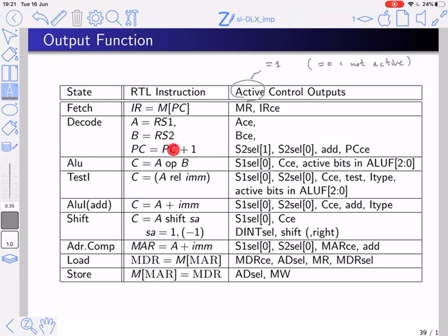And so you're adding a PC and 1, the output of the PC and the constant 1 are added, and the outcome of this addition, the sum, is sent to the input of the PC, which samples this input and stores it because it gets a clock enable.